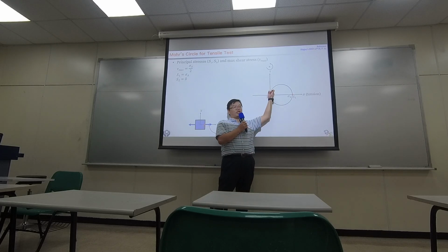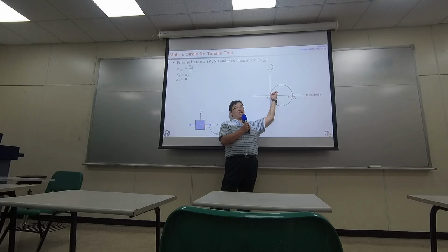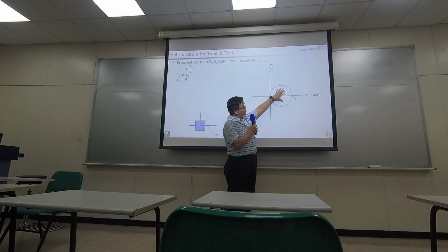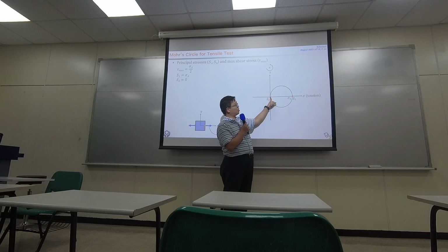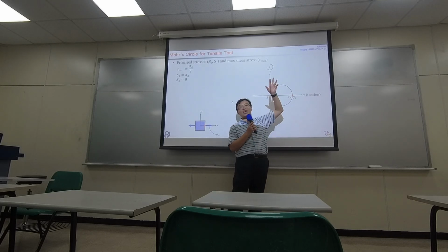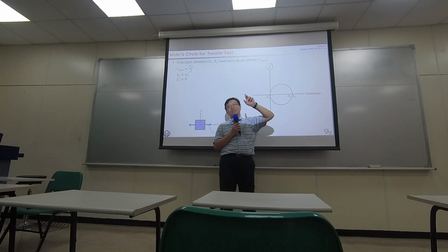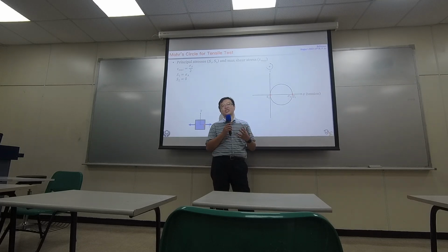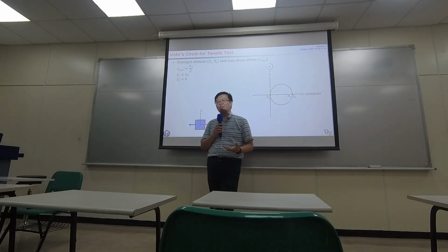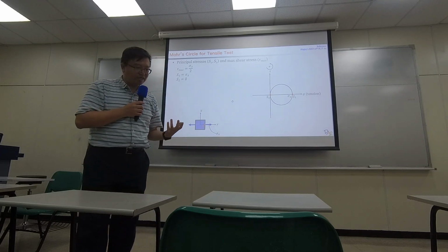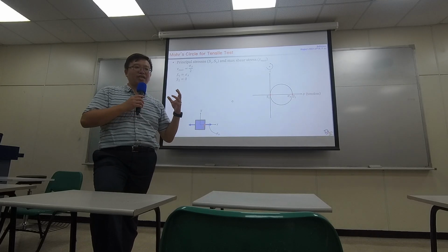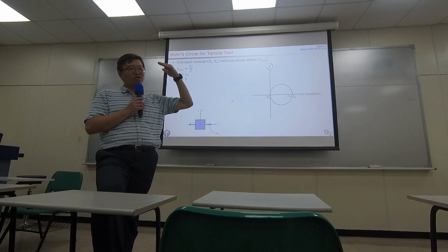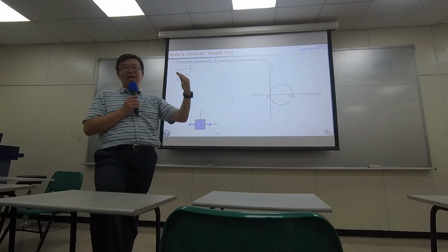So initially, the Mohr circle is like a small dot. And when you start the machine and start to pull, the Mohr circle starts to expand. But S2 remains 0. S1 basically moves toward the right, until one day S1 reaches the yielding point. That would be the position where we consider this piece as failing, because in our design, like I said yesterday, we only focus on elastic loading conditions. We don't want to see nonlinear deformation. We only want to keep it inside the linear, elastic region.